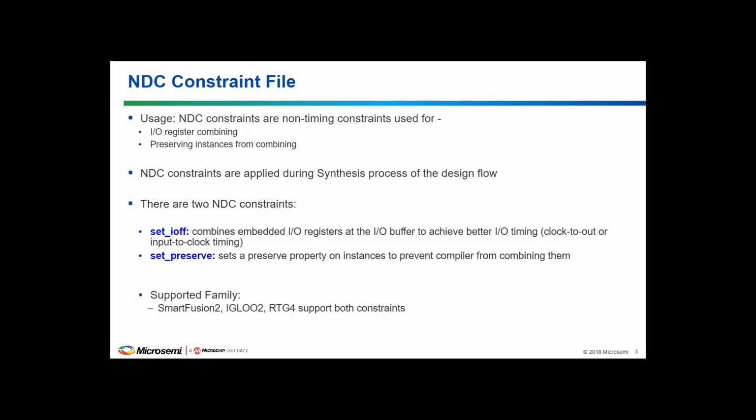Both constraints are supported in SmartFusion 2, Igloo 2, and RTG4 devices. PolarFire devices only support set_preserve constraint. Because I/O register combining is available in layout option, you just need to apply proper timing constraint in that case.